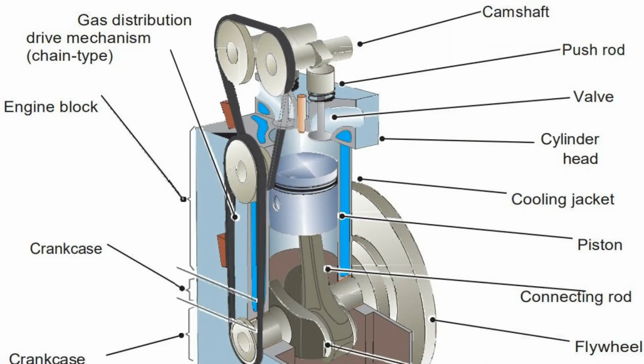After completion of the lubrication cycle, the liquid flows into the oil receivers of the power unit, from where 80 to 90% of it is directed to the autonomous tank by means of the pumping segment of the main oil pump. There is a radiator on the oil path where it is cooled. In winter, during the first minutes of engine operation, the oil has not yet had time to warm up to operating values, and in order to prevent the radiator from being destroyed, a bypass valve is activated.